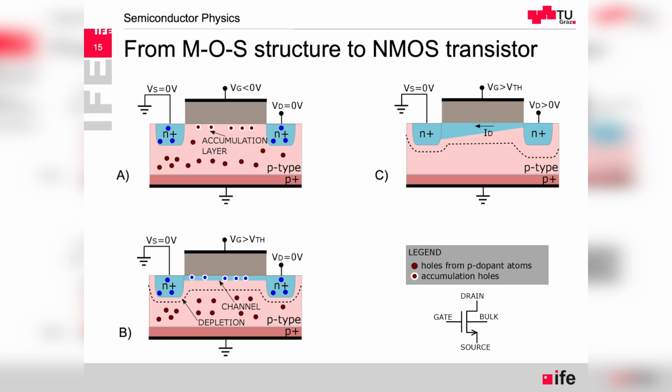So there can be some charge transport along this border line. On the other hand, we have learned already about the diodes and the fact that in the reverse bias condition, the diode also has a certain current. And we have here the two diodes between p-type and n-plus materials, so that also contributes to the leakage current.